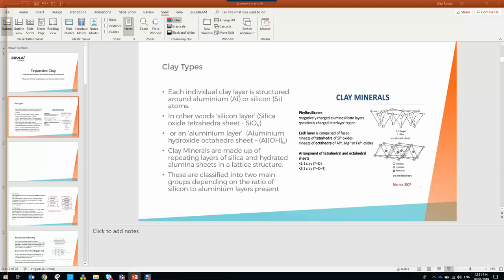So you can put it in, you just get rid of the sand or crusher dust for half a metre, pour your bentonite in or your natural clay, and basically you try and stop it about every 10 metres just so water doesn't track back in. And particularly electricians are the worst at this because they will just dig trenches straight towards the building, generally downhill. They won't backfill them properly, and it's just, they just don't care.